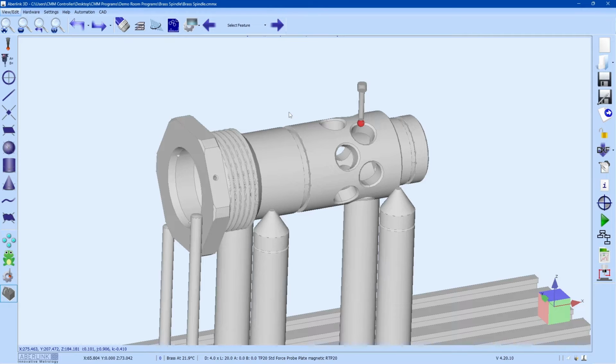Now, what I do find is if you really must follow the concentricity call out, one of the best ways to do it is still to set up using cylinders, but then use the construction method to do an intersection plane and an intersection circle. This was covered in the part 1 video, but I'll go over it again now. And this gives you a circle that is actually true to the diameter itself.